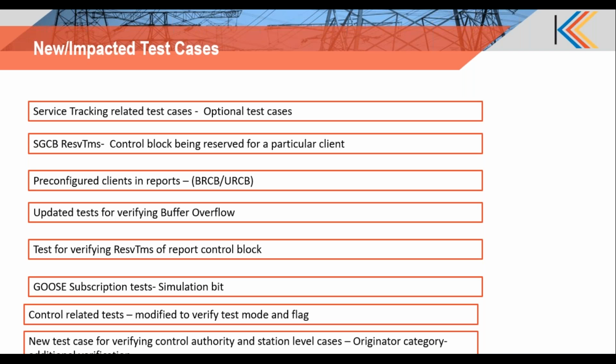Then we have this reserve times. So that's another test that got updated in addition to the existing testing. So for the setting group control block and for the report control block, we have this reserve times, which is basically an amount of time where that particular control block instance will be reserved for a particular client. So we have an additional test case that makes sure that the response of the IED is correct.